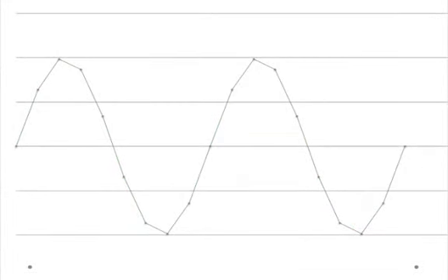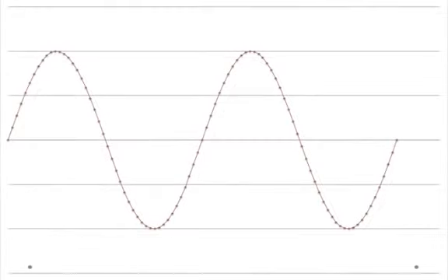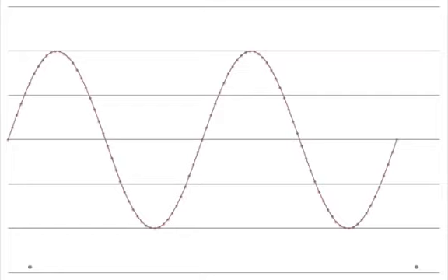Specifically, when digitizing a sound signal, it is measured at different points of time, say every second. Each measure generates a value to represent the sound. This value is then coded as a sequence of zeros and ones. These value points can be used to generate a line that is an approximation of the original sound wave. You can think about this process of regenerating the sound wave from the stream of zeros and ones as the process of connecting the dots.